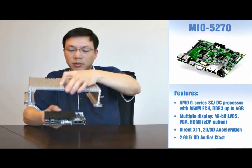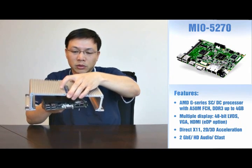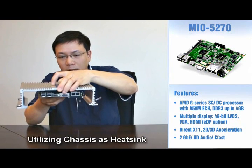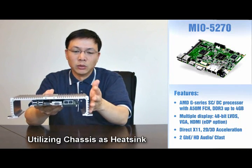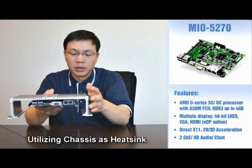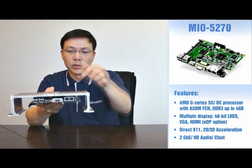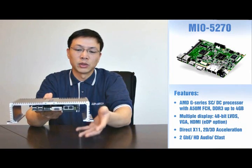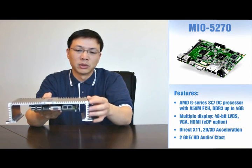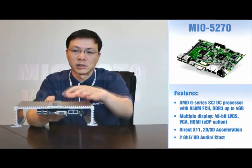In this case, this is one of the Advantech products as well, but this is for general sourcing idea. You can use the chassis, if it's an aluminum plate with a fin, as a heatsink adapted to the heat spreader plate, and then you can take the heat outside of the chassis without having to open up holes, or if there's limited airflow, you can still properly conduct the heat out of the chassis.